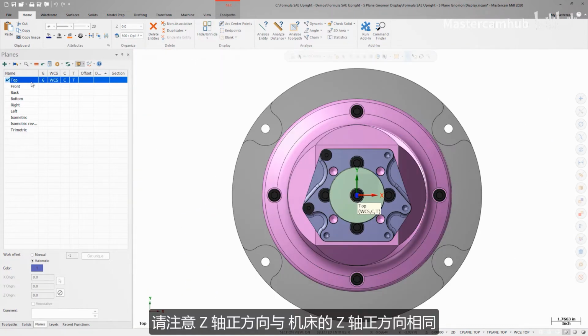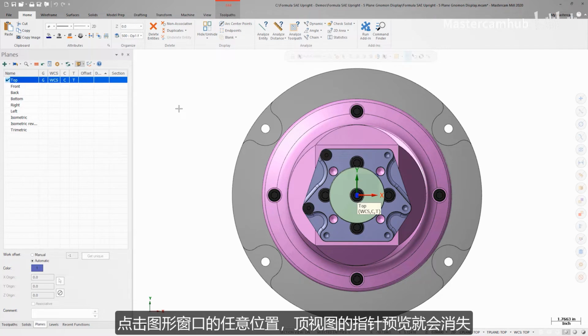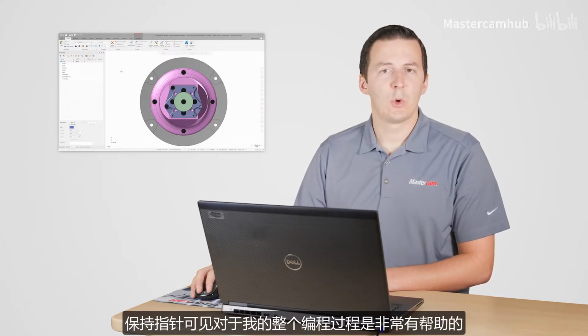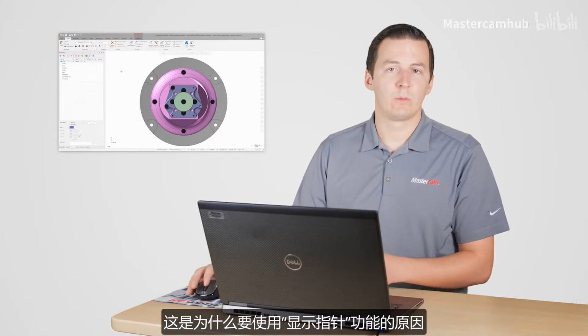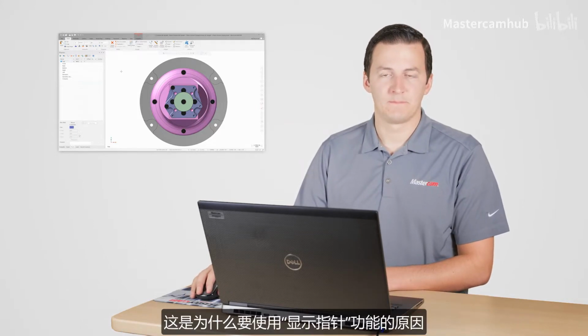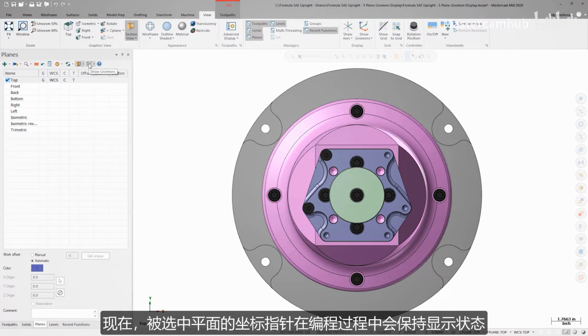Note how Z positive is facing in the same direction as our machine's Z positive, and the X-axis is parallel to the front face of the top plate. When I click anywhere in the graphics window, the Gnomon preview for the top plane disappears. Being able to keep the Gnomon visible for my entire programming session can be extremely helpful, and this is where the Show Gnomons toggle comes in. I can go to the View tab or the Planes Manager to enable Show Gnomons, and now the Gnomon for the selected plane will always be displayed.